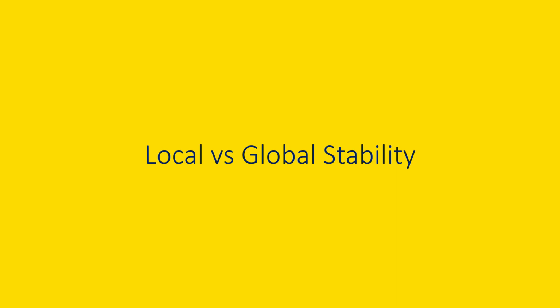It's important to note that all the stability definitions we studied so far are local, which means they only give us information about the behavior of an equilibrium when we are around the equilibrium. But there is no guarantee that, for example, for all initial conditions in the space, the solutions tend to the equilibrium and therefore the equilibrium is globally asymptotically stable. We now propose conditions for global stability and start with global asymptotic stability.